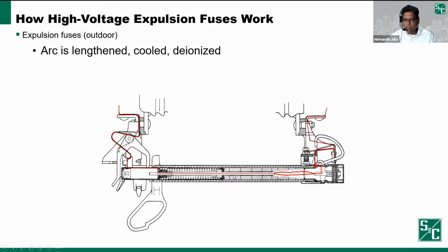Remember that spring I was talking about earlier? That spring is now expanding. You can notice that. Now this arc is being pulled into this solid material chamber. The arc is really hot, and it interacts with the solid material and generates some gases. Those gases aid in the interruption of this particular arc.